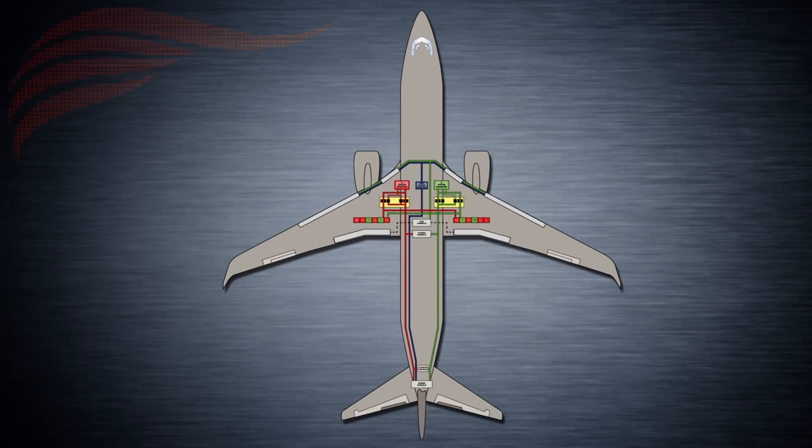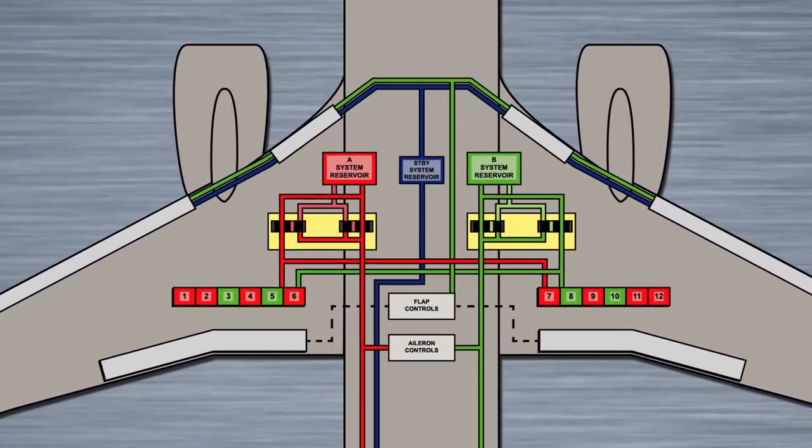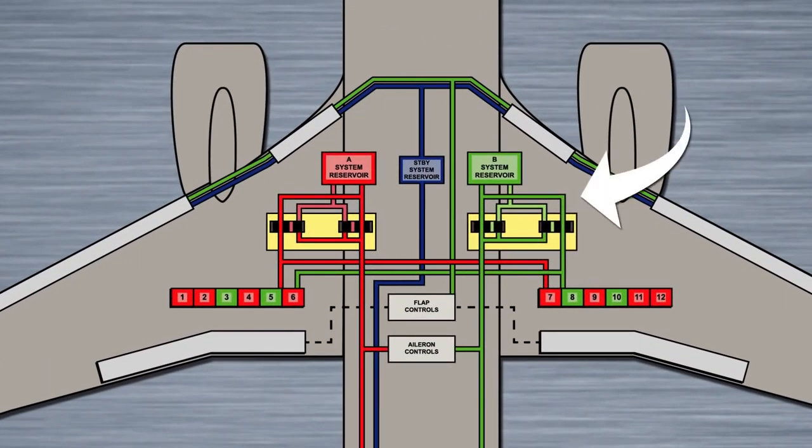Trailing edge flaps may be controlled in one of two ways: hydraulically or electrically. During normal operation, the hydraulic system B powers all trailing edge flaps. System redundancy is provided in a way by which if there is a hydraulic system B failure, trailing edge flaps may still be operated electrically through the alternate flap extension mechanism. This will be discussed further during this lesson.